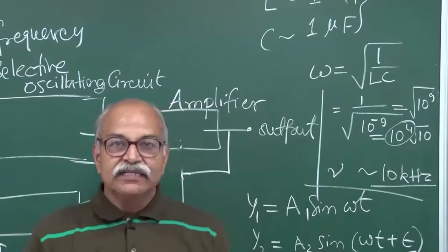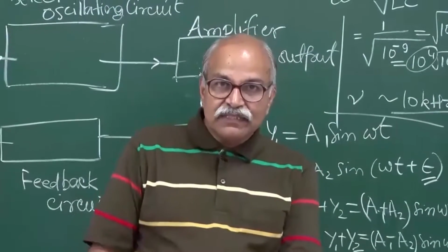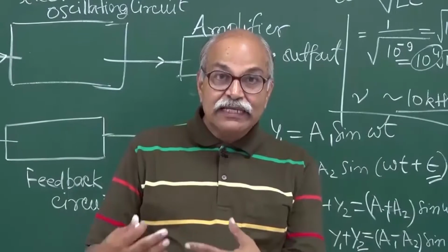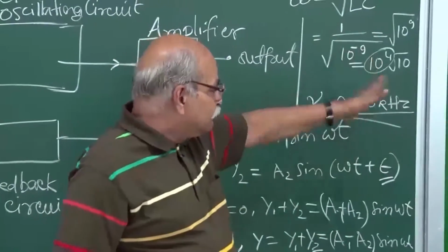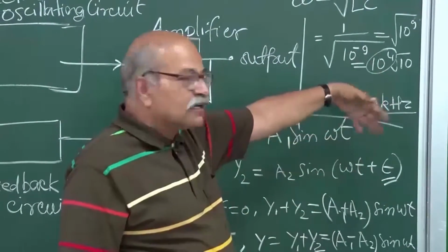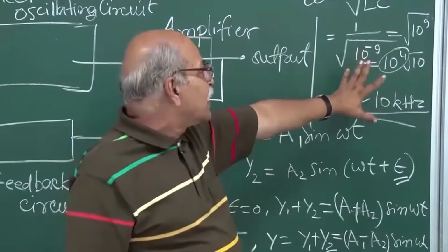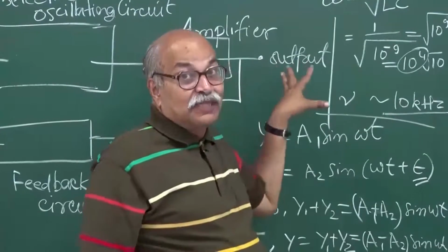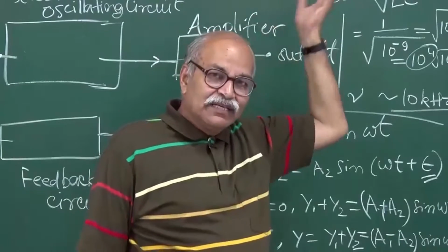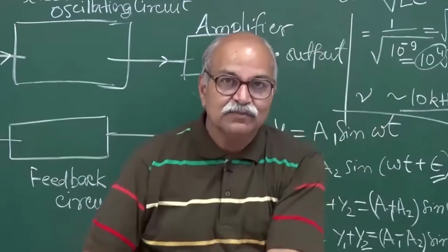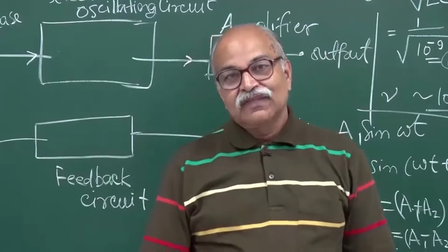So in this oscillator that I showed you, it had a low frequency range, high frequency range, middle frequency range. So that LC oscillations that I had described can be used in this middle frequency range, which is around kilohertz, 10 kilohertz, 100 kilohertz, like that. So for that, this LC thing can work, but for lower frequencies or higher frequencies, something else has to be used, and that must have been used in this box.